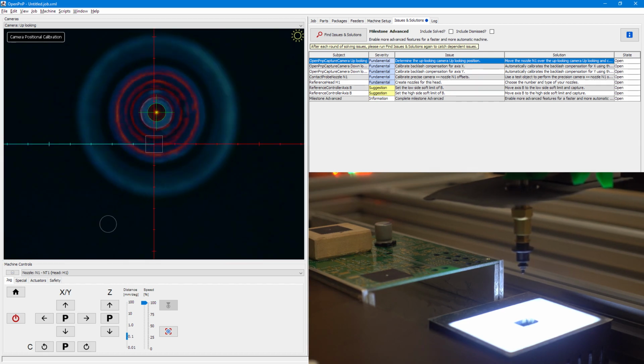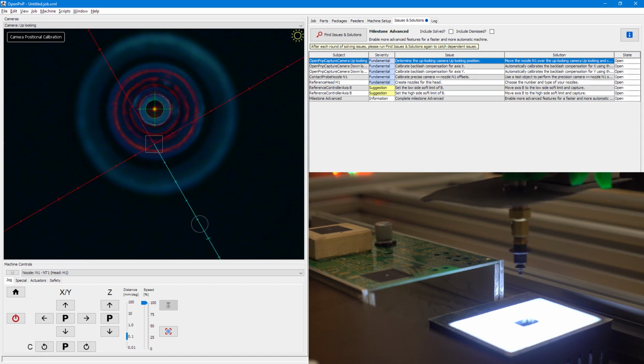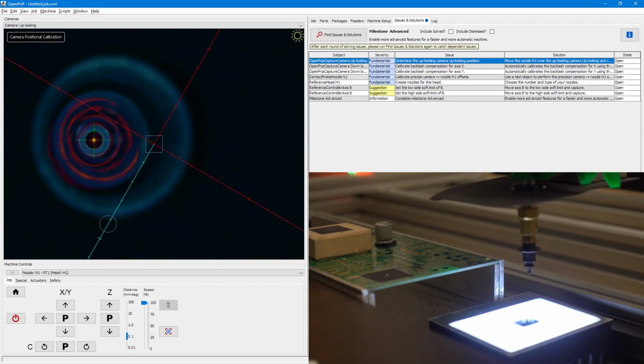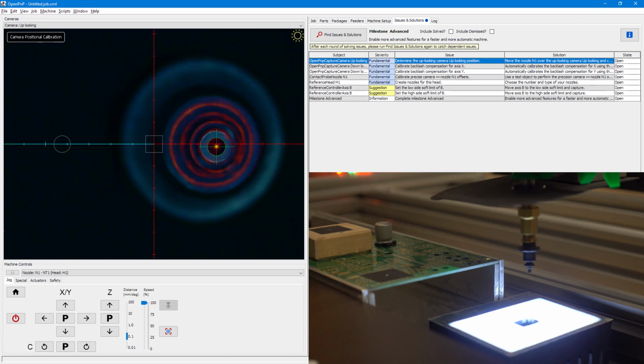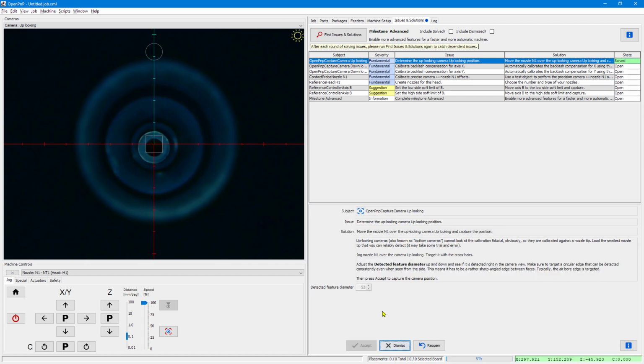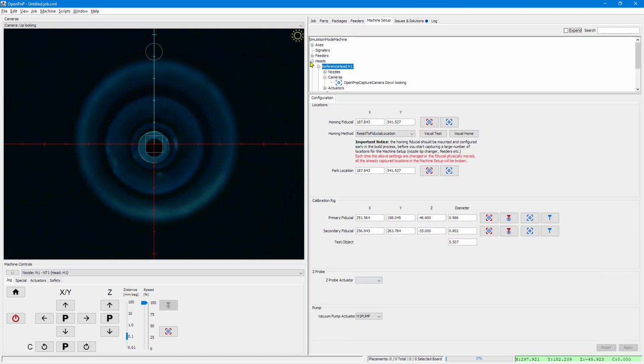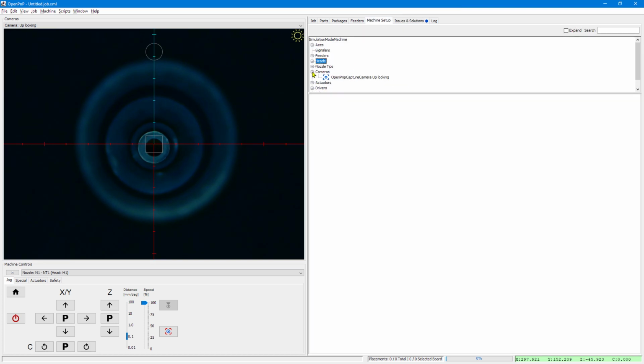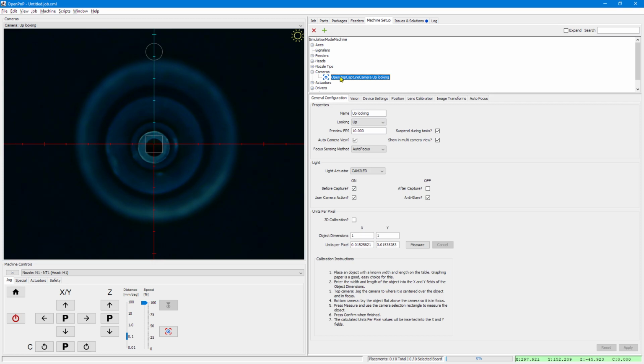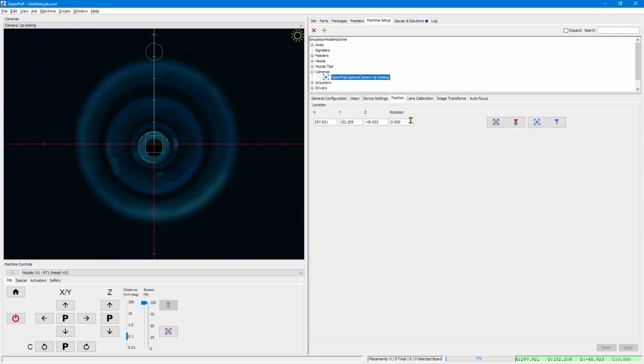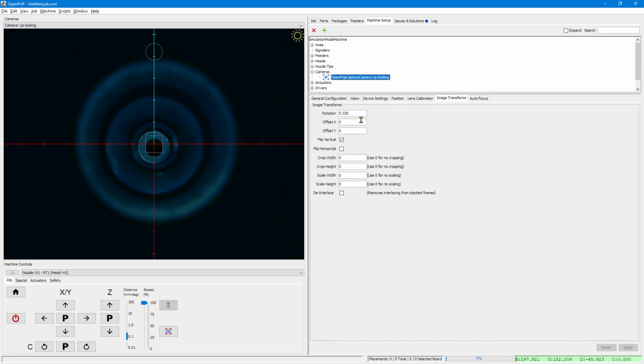These calibrations can not only set the units per pixel perfectly, but they also set any mirroring or flipping flags and camera rotation, so you don't even have to do that. You get your two-dimensional units per pixels, you get the position of the camera precisely, including the Z, and you get the rotation of the transform.